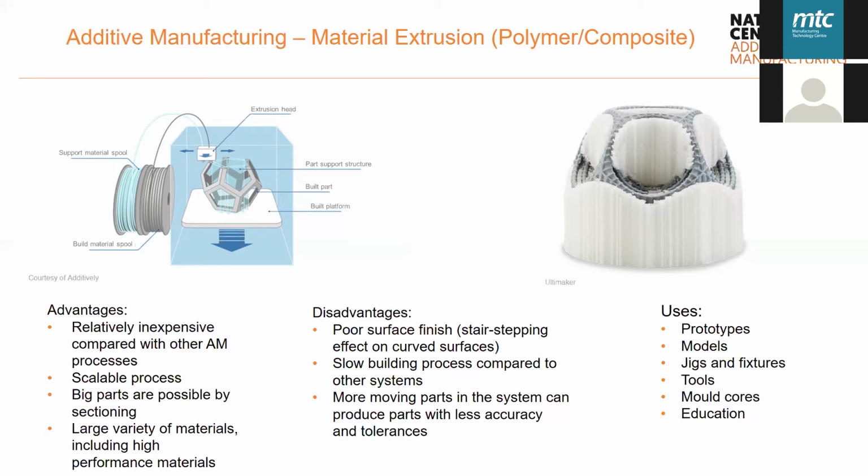So we mentioned composite previously. Some of the systems actually manufacture using a composite material, which significantly improves the strength of these components. Some disadvantages are that usually you tend to find poor surface finish and stair stepping due to the high layer thicknesses used for deposition.